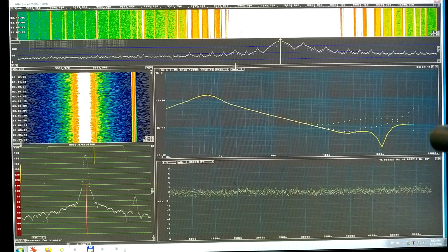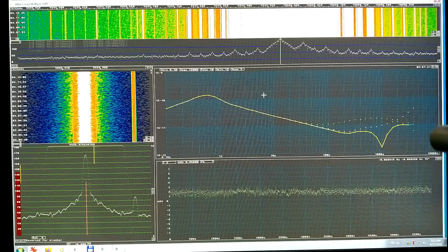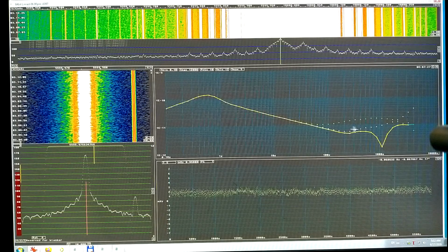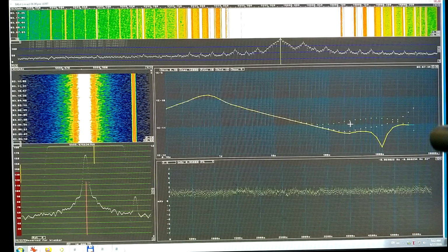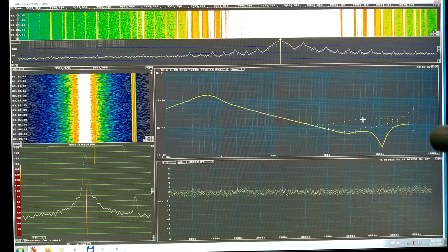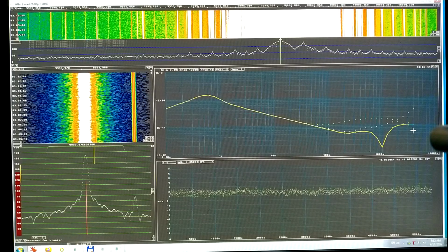Here is 4 hours with the rubidium source. It is stable now, and the Allan deviation looks reasonable. I think that above 300 seconds or so in this region, the statistics is not at all good enough. The noise of the oscillators probably goes up like that and not down like that. It's just a statistical phenomenon.